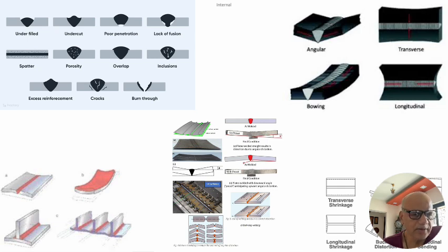And good welders I have seen, they are able to get them improved while they are welding only. Either they will stop immediately, do whatever correction is required either in the gas or in the shielding or in the angle of your torch or electrode or your other cleanliness issues if they are there for the porosity, and they will surely be able to improvise it. But otherwise you will have to wait for X-ray to happen or a dye penetrant for a fine porosity which is exposed to the surface.